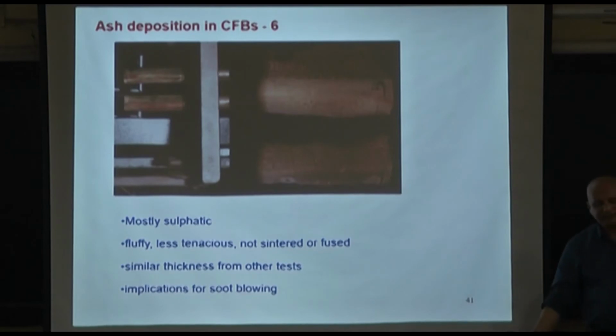So it's the organic sulfur which gives rise to sulfur dioxide, which you need to capture by calcium oxide, limestone, dolomite, etc. Dolomite, by the way, is a mix of calcium carbonate and magnesium carbonate. Magnesium carbonate also breaks down to magnesium oxide and captures the sulfur dioxide as magnesium sulfate, not to the same extent as calcium oxide capturing it as calcium sulfate.